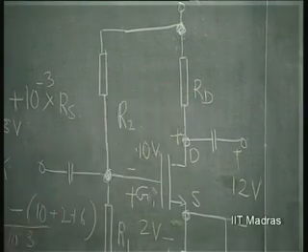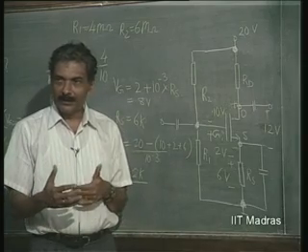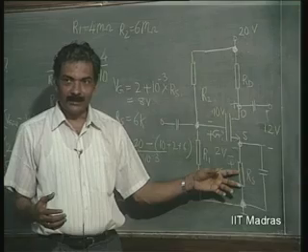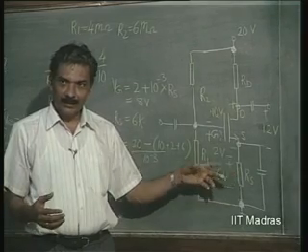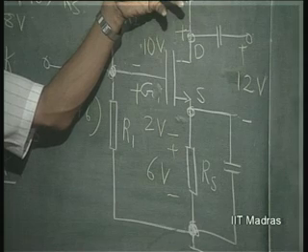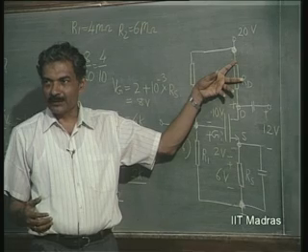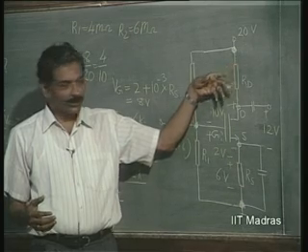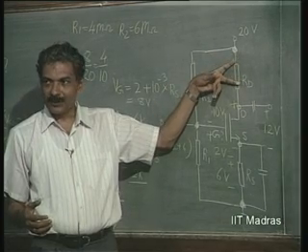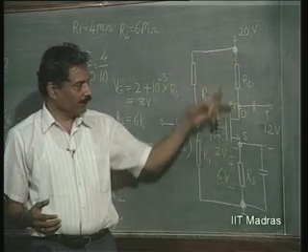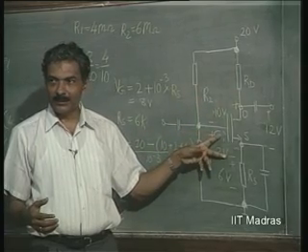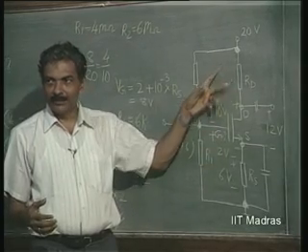So, you can select RD as a high resistance compared to this. If you have taken RS itself as, let us say, 20 kilo ohm, we would definitely select this also of the order of 20 kilo ohm. So, 20 kilo ohm means a further 20 volts drop. So, 20 plus 12, 40, 52.